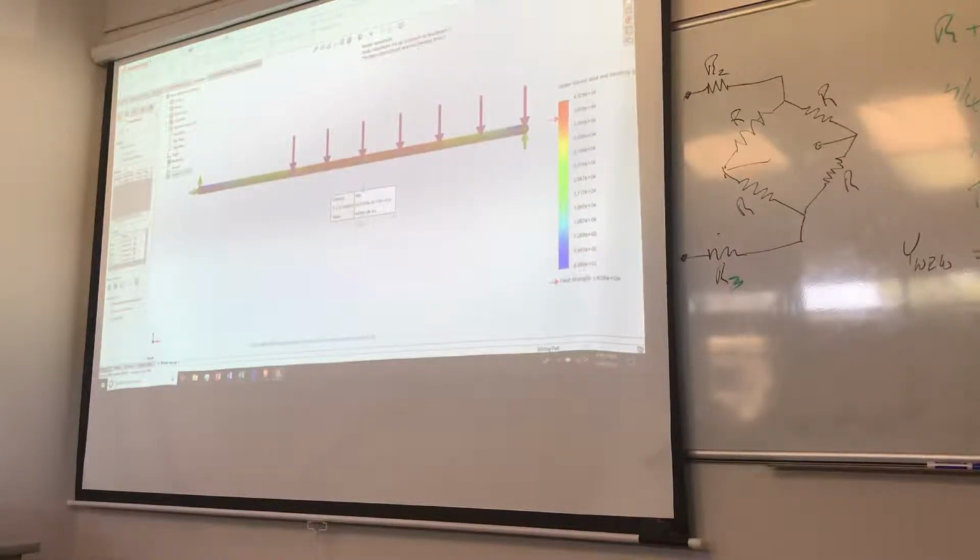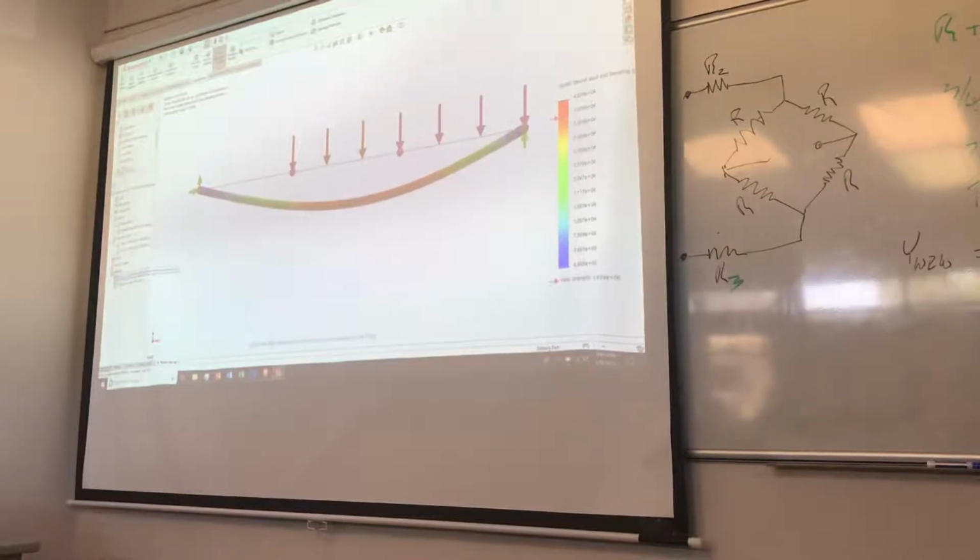Okay, so anyway, we're actually looking at axial and bending loads on it. There are other things you can look at. You can go edit your definition. We can look at axial loads, the bending directions, the bending stresses. We can look at a torsional stress if there is one, and we can look at the shear stresses. All of those are possible. I'm going to leave the axial and bending in there. It's not a bad thing to look at.